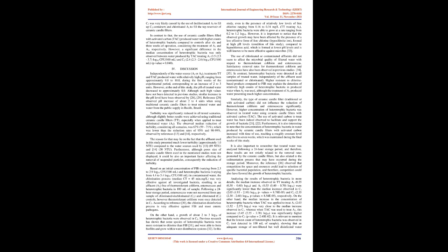In contrast to that, the use of ceramic candle filters filled with activated carbon, TAC, produced water with higher counts of heterotrophic bacteria compared to controls after 6 and 3 weeks of operation, considering the treatment of A1 and A2, respectively. However, a significant difference in the median concentration of heterotrophic bacteria was only observed between water produced by TAC treating A2, 3.5, 2.5 to 3.7 log10 CFU/100 ml, and C2, 2.4, 2.3 to 2.6 log10 CFU/100 ml, p-value equals 0.048. For discussion.